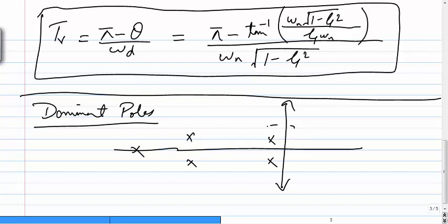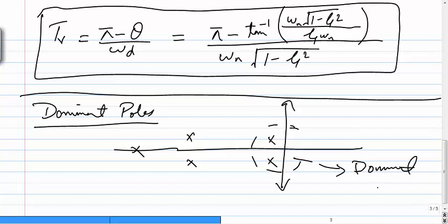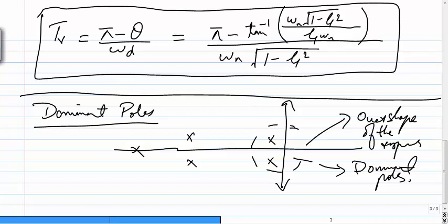The poles that are near to the origin are known as dominant poles, and because of slow convergence, they determine the overall shape of the response. This information is used when we have a higher order system.